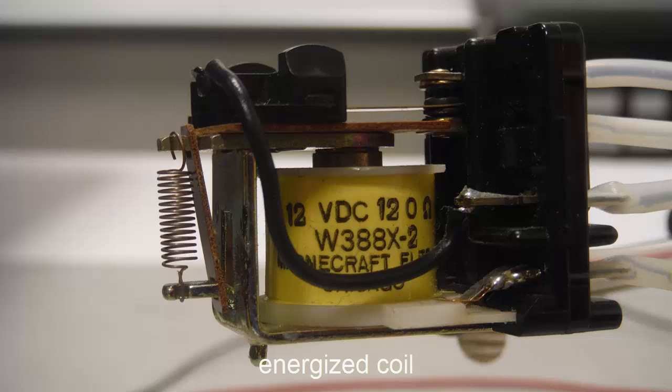When the coil is energized, it pulls the lever arm down and the common in the center is disconnected from the normally closed contact at the top and making contact with the normally open contact at the bottom. This is associated with a characteristic audible click that can be endearing or equally maddening depending upon the application. Solid-state relays, as we'll learn in later lectures, do not click because there's no moving parts to clack.